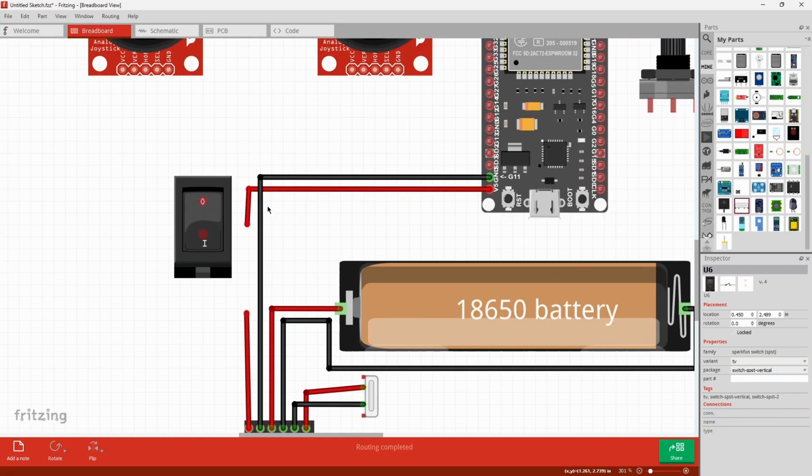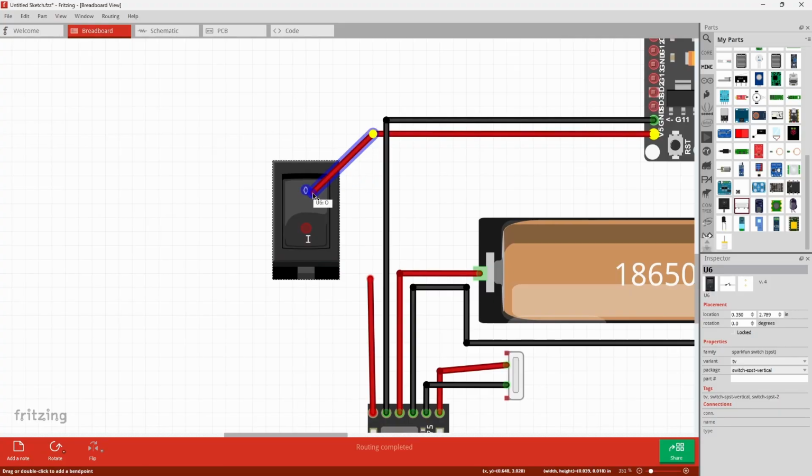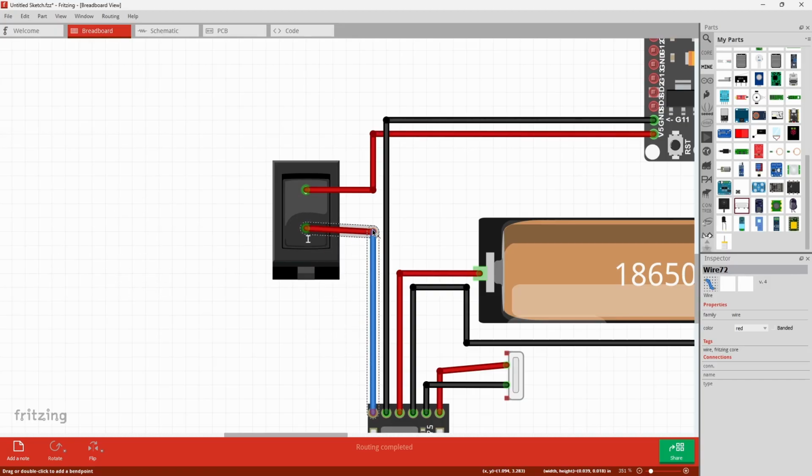Of course, there's a switch there which would allow you to power off and power on the circuit in general. This switch comes in between the 5V and GND of the ESP32 because that's where the load directly comes to. For this particular chip, if there's no load, after some time it goes off. It also has its own personal power button, so maybe the load is below, I think, 50 milliwatts or 50 milliamperes, somewhere around there.